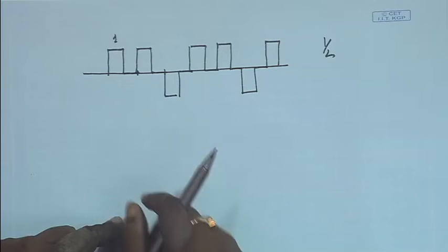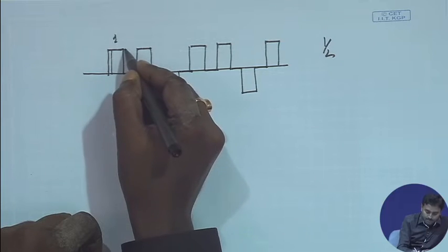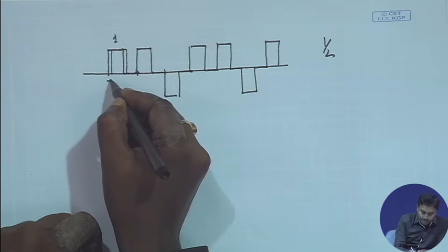So, now this is a power signal for us. All we wish to do is calculate the time autocorrelation function, right. So, that is our target. That means we have to shift this signal slightly, and then we have to multiply it. So, let us say we have shifted it by an amount tau.